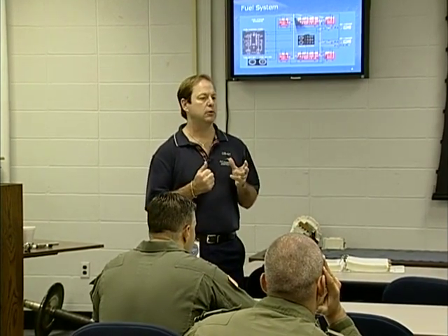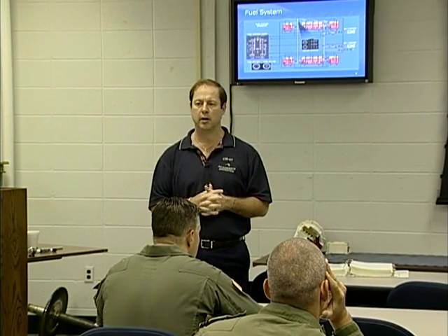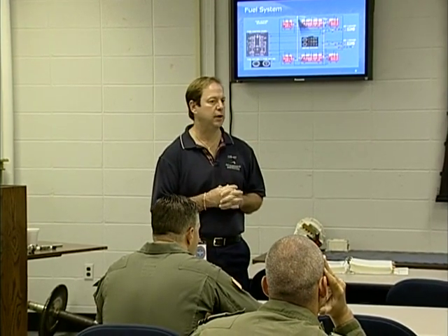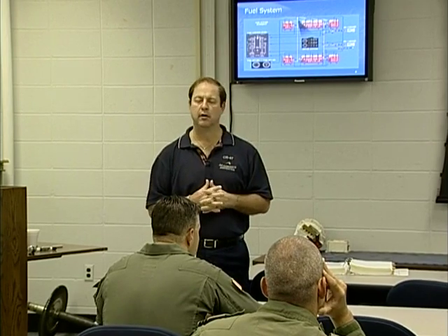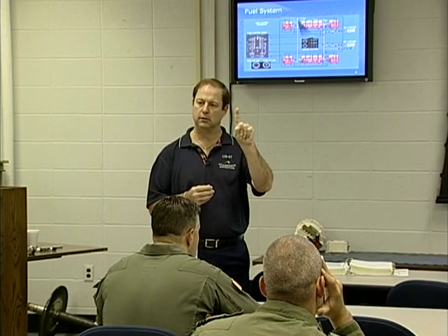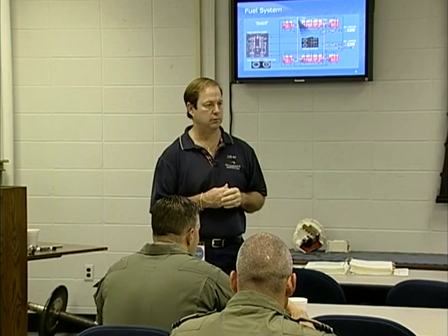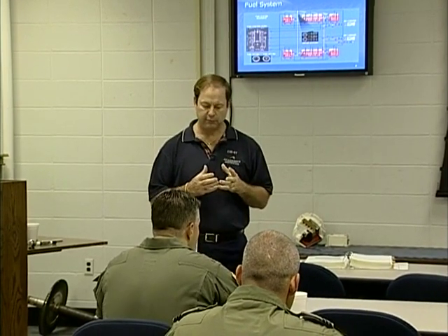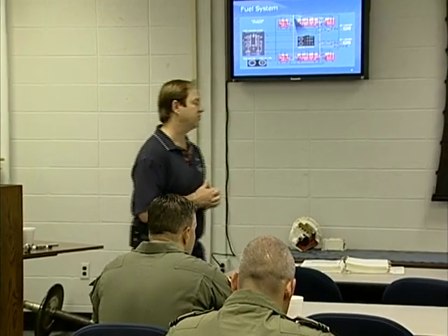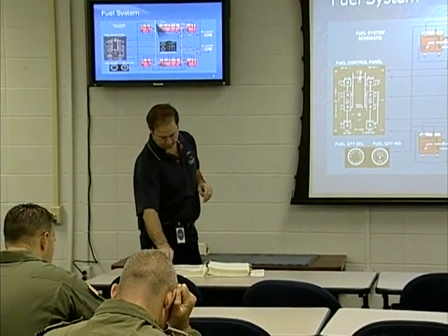But keep in mind, the transference of fuel from the aux tanks to the main tanks is nothing more than what type of operation? What did we just discuss? There's 2 operations, feed and refueling. It's a refueling process, gentlemen. By thinking about it as a refueling process, you're going to understand the pieces and parts and everything's going to make sense. Okay? The airframe system furnishes fuel to 2 engines.